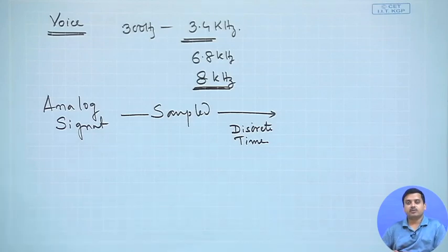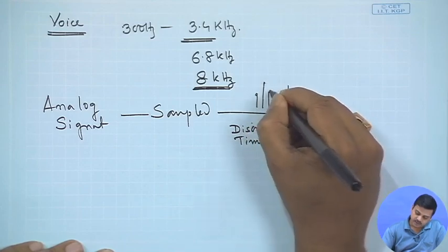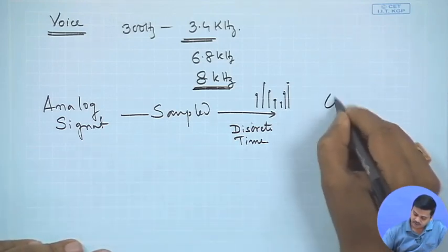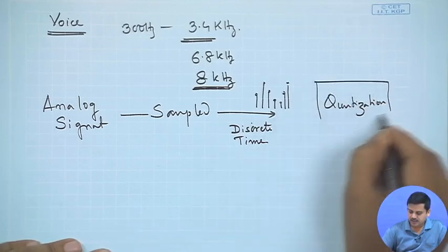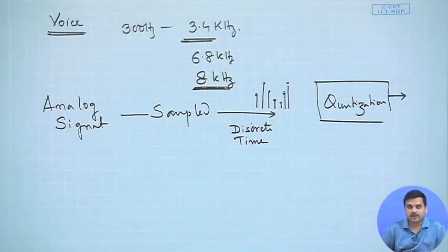Now, if you would remember, in one of the early lectures we had said that if at all one could communicate between the transmitter and receiver or through a channel, one could do it through binary interfaces. That was one of the statements that we said was due to Shannon. So, what we have with us at this point are still samples. Of course, those are discrete in time, but still continuous in amplitude. The next step, which is the quantization, is the next step which is used to generate sequences which have discrete values of amplitude.